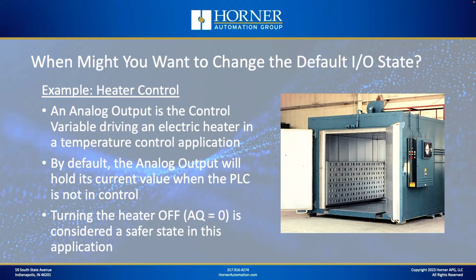But maybe you think it's safer for that analog output to go all the way to minimum to turn the heater all the way off when the PLC is not in control. That's a perfectly valid approach. So you can set the default I/O state of that analog output to be minimum.